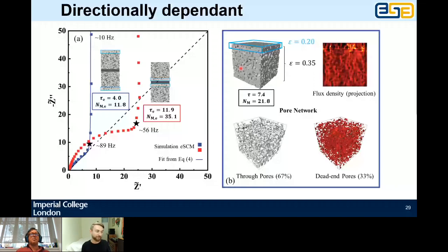And you can see, if you now look on the left-hand side of the 2 Nyquist plots, when that dense layer, i.e. the low porosity region, is sandwiched either side of the separator, so right in the middle of the cell, the total transport resistance experienced is much higher. That battery is now facing severe transport losses in the electrolyte phase because you've blocked off all the pores right next to the separator. And conversely, when you turn it around and put the dense layer next to the 2 current collectors, you now have a much reduced impedance from that transport process.